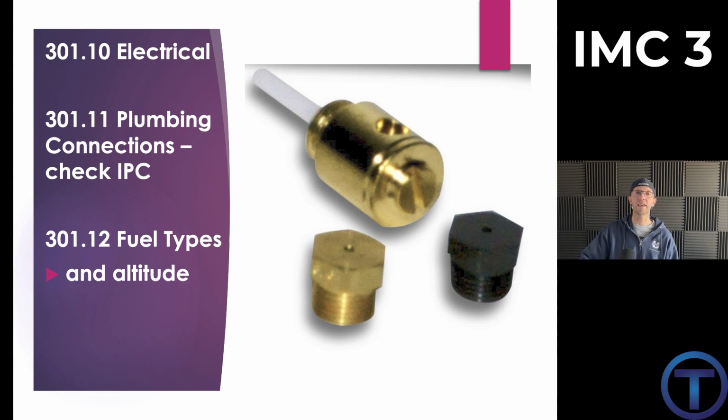It's going to burn differently. It's going to damage the burner. It's going to damage the appliance. So it's really important to have a handle on this, right? To know when I'm installing an appliance, it has to be rated for that fuel. And if we go to the altitude, the orifice can also compensate for that. Where we have different atmospheric pressure than at sea level, we're going to need to let that gas through at a different rate so that it will burn properly.